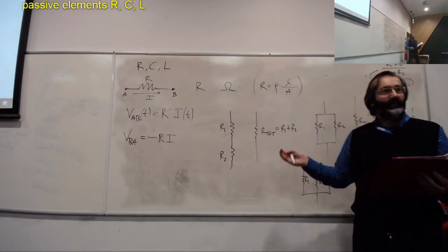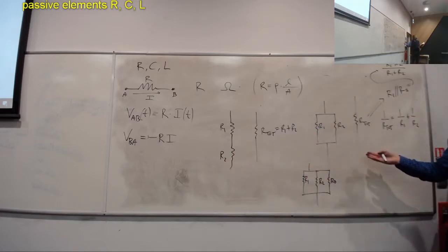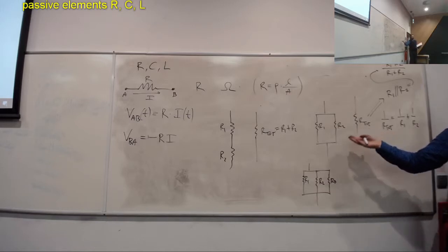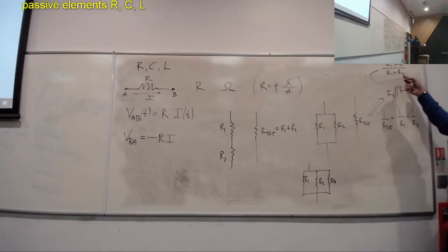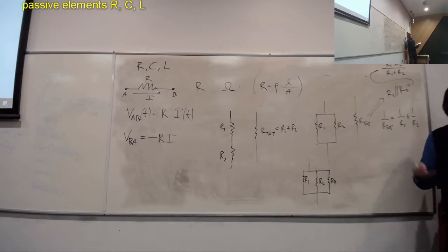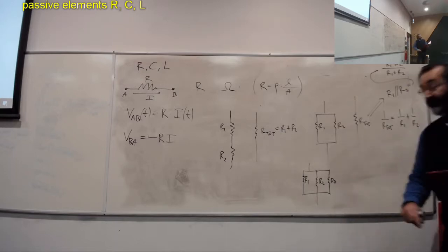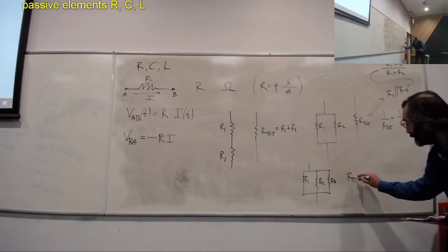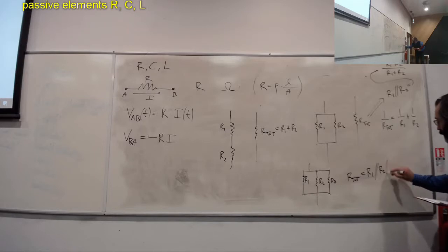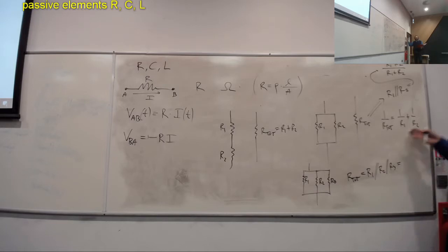It's the sum. When we have the parallel of two resistors, the total resistance will be dominated by the one that is smaller. And this comes from here. Okay? That's something to keep in mind. When we have a parallel, the effective total resistance is near to the smaller of the two. When I have 3 now, I will indicate R total as R1 parallel R2 parallel R3. Obviously, it follows this formula, simply with another term.